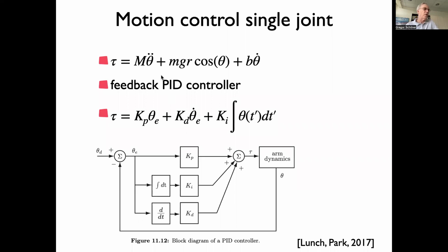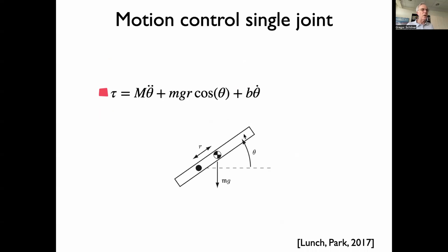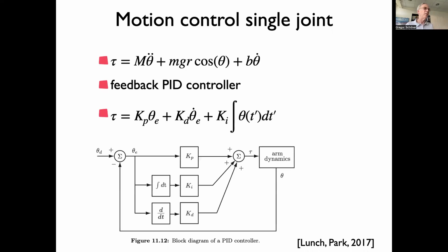And the integral control is sort of the most problematic one, mathematically speaking. What the integral controller does is that it accumulates error. What helps here, for instance, is if there's something really missing, like a load that you didn't plan for, an extra load here that makes the element systematically offset from the desired state, which you didn't take into account when you designed the system.